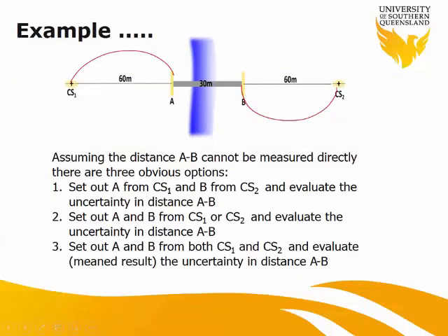Good. So what would be the uncertainties we have? There are some inputs given in the study book that you can go and have a look at, like the accuracy of the instrument. There are some known elements like uncertainty in setting out the instrument and setting up the target. If you look at those errors, we can sort out the uncertainty for each position.